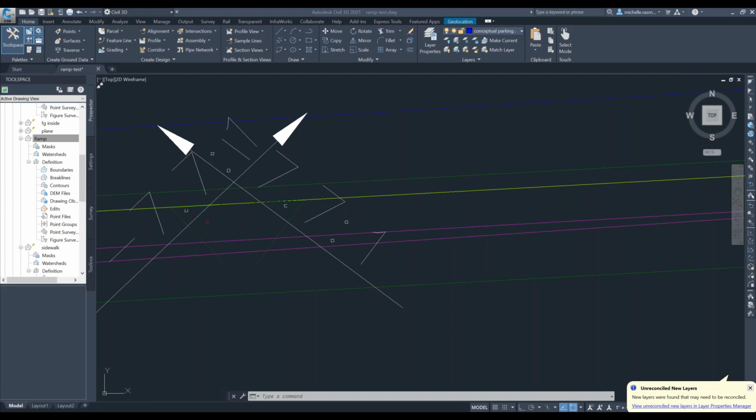When we do it with feature lines, the curve itself may be drawn with a feature grading group, similar to what you've done, but we will draw the ramp itself and the wing walls as a solid feature line, which will control the slope on the ramp itself. So the 10-to-1 slope or the 12-to-1 slope, we could control basically by using just a feature line. From that, we are allowed to control the cross slope and the running slope of both directions of the ramp itself.